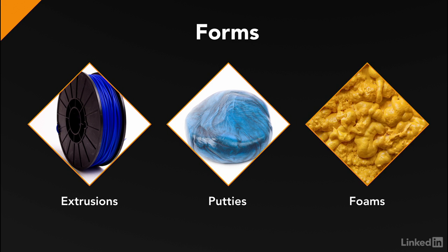Foams are special because of the way that they're made. Air is introduced either by mixing components that create a chemical reaction or by being frothed up mechanically with an inert gas to encourage bubble formation. Foams can be made from either thermoset or thermoplastic materials to create strong and rigid foams or soft and pliable ones. An interesting thermoset elastomer foam is polyurethane foam, which combines highly squishy pliability with high toughness. This addition of air creates a great application for flotation devices, impact, and sound insulation due to its low density.